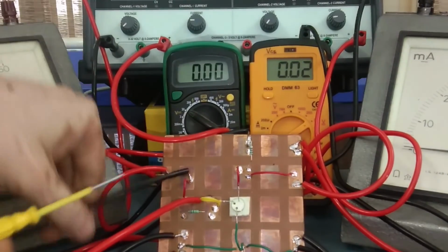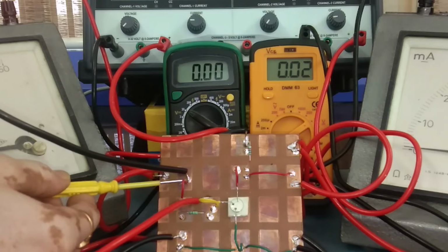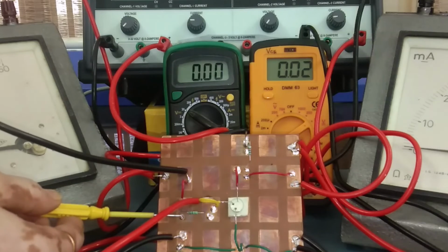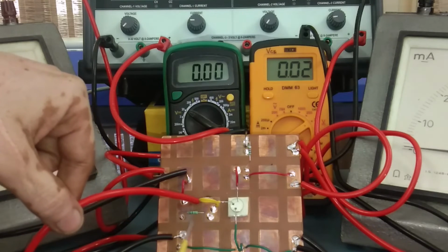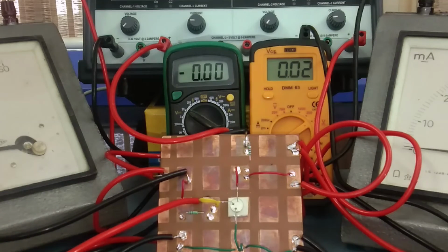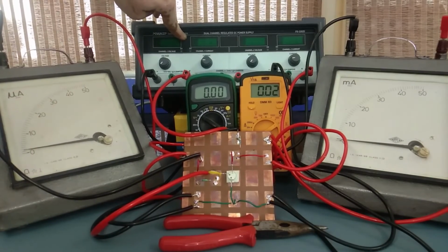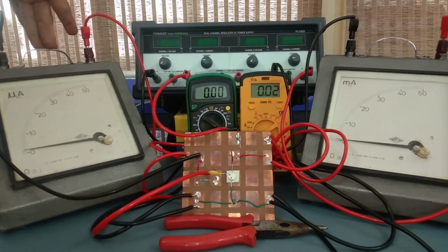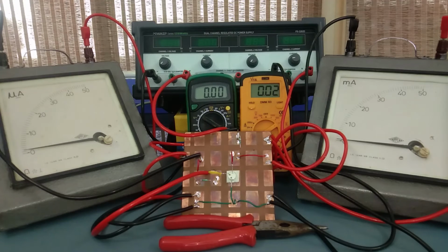Now you can find the other terminal, the negative terminal of the microammeter, is connected to the base resistance. One terminal of the base resistance is connected to the microammeter, and the other terminal is directly connected to the base. What does that mean? That means that whenever we apply voltage at the power supply end, that voltage makes the current go to the base through the microammeter and the base resistance. That means your base circuit is safe.